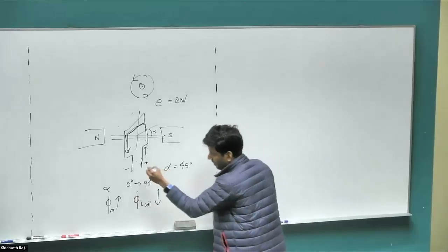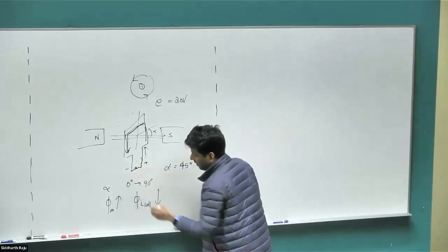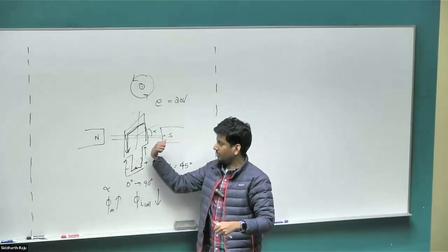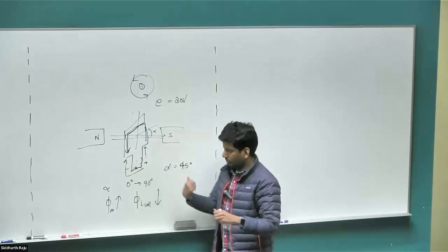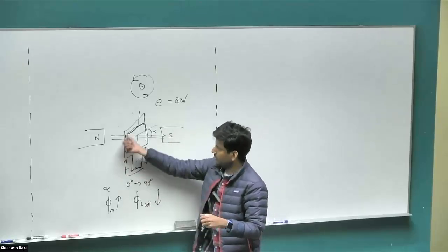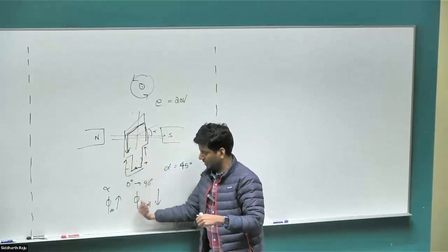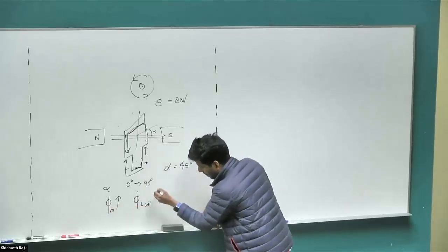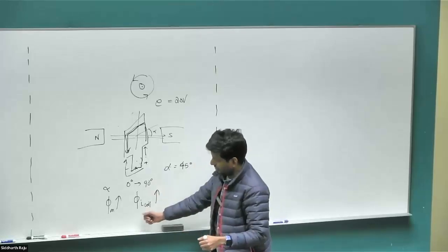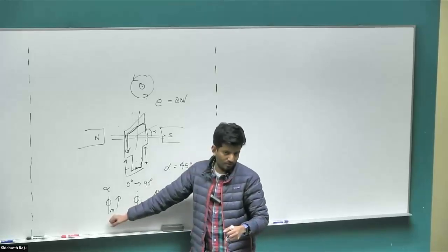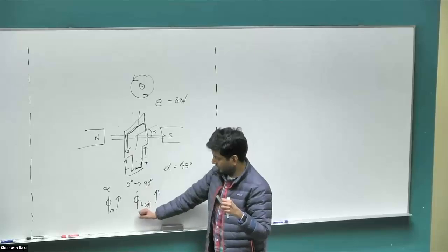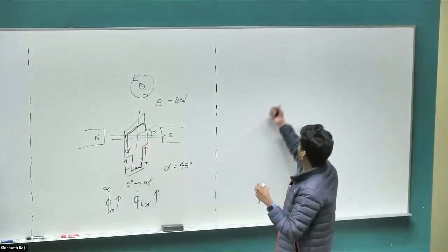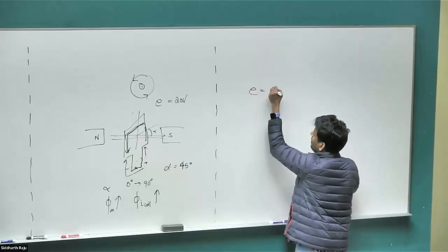No, the problem is if I put it in this way, and I put a resistor here, the current would be in the opposite direction. If the flux is starting to increase, the current will start to flow in this coil, and that flux is going to be in the same direction as the magnet's flux. So the coil is going to add on to the external magnetic field. Now there is a problem, because the sum of these two is what is interacting with this coil. That would lead to even more increasing EMF.